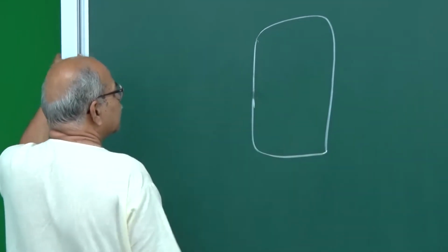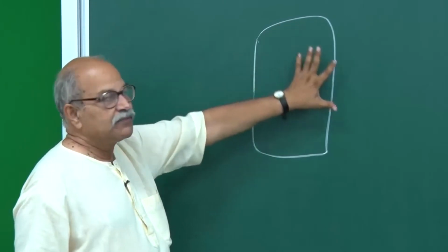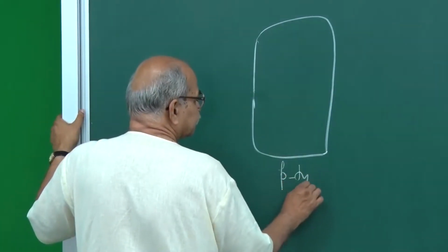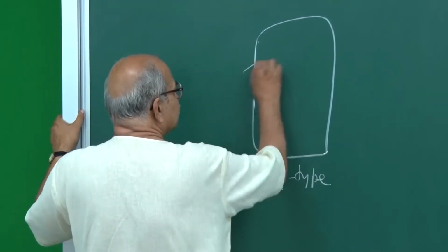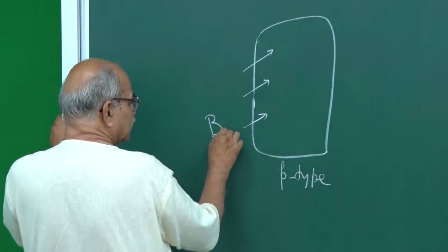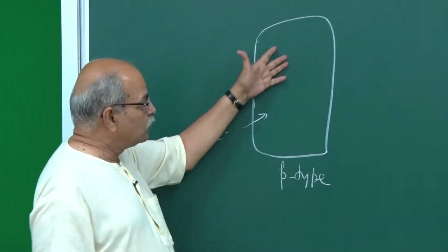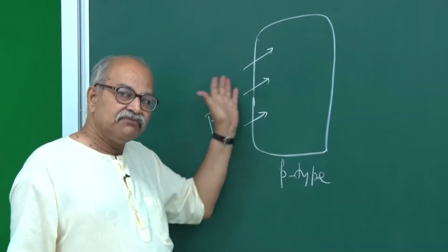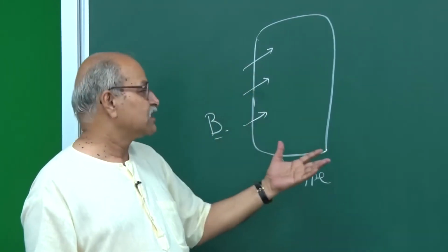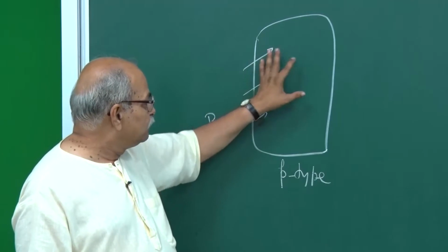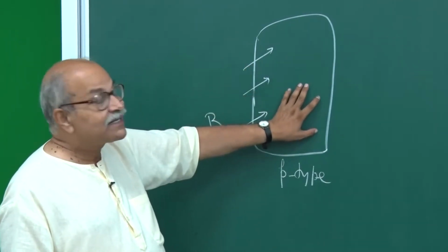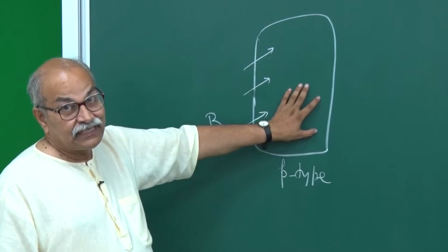So, that is the starting material, and with this starting material, the first thing is this entire wafer is made either p-type or n-type, this whole thing. So, let us say we make it p-type. To make it p-type, you have to diffuse trivalent impurity like boron. So, it goes there. Here also you have very controlled processes. There are several processes by which you diffuse these impurities, and at the end you retain that silicon crystal.